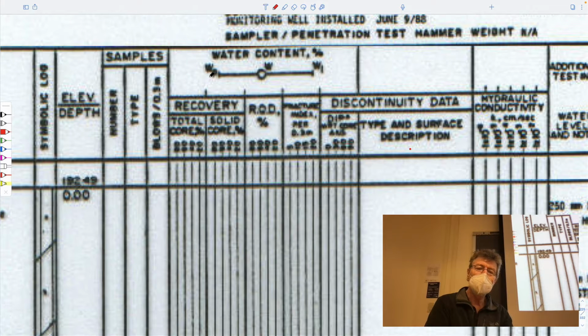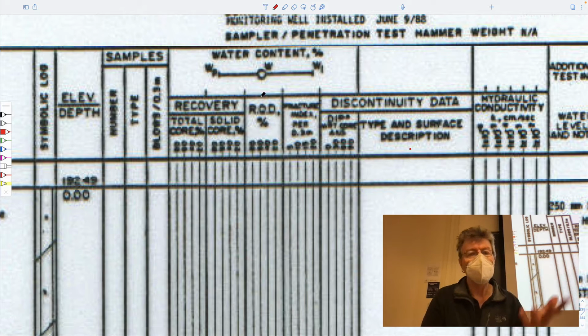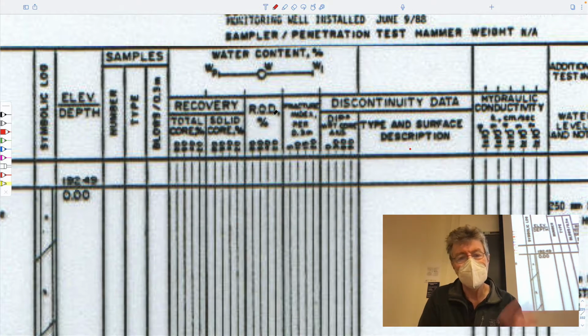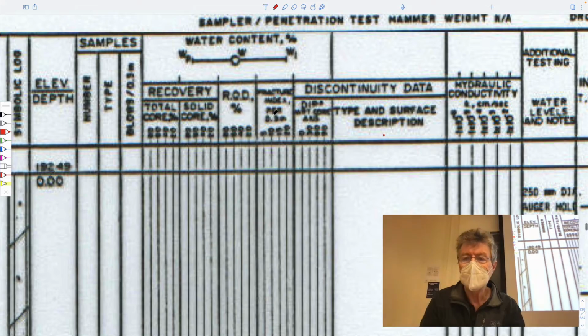And the plastic limit is when you take that clay and roll it into a sausage, and you can no longer roll it into a sausage which is probably 1/8 of an inch thick, or perhaps it's 1/4 of an inch thick, I can't remember. So you keep adding water or drying it until that occurs. The natural in situ moisture content is somewhere between the liquid and plastic limits, and that says something about the behavior of that clay that you'd expect if, for instance, you're putting a foundation on top of it, though not for the things that we're interested in.